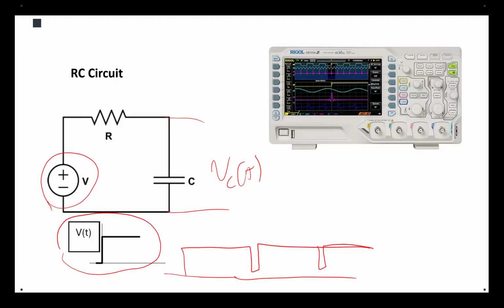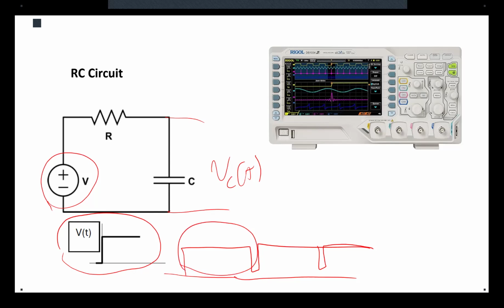Remember, if you calculate your time constant, and you already know that you need 5 time constants to reach the final value, the only thing you need to do is make sure that the on time of your pulses is more than those 5 time constants, so you know you can reach the final value. Are we good? So how can we do that?